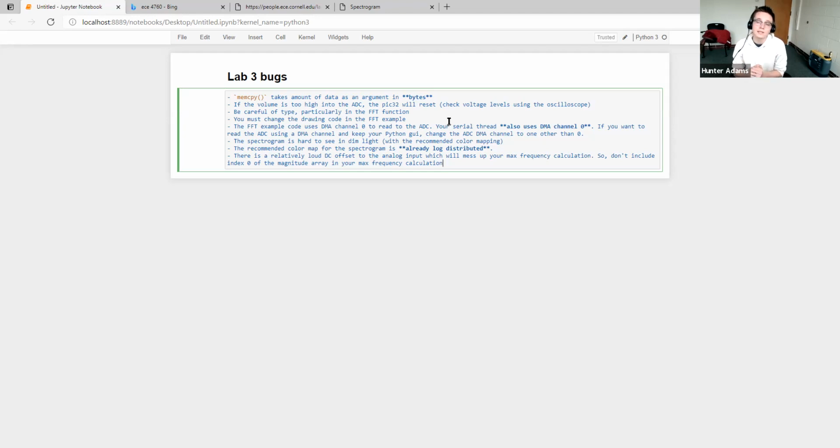And what you will find is the accuracy with which you can report the max frequency will improve as the frequency range of your spectrogram decreases, because there are fewer frequencies per bin in the output. So you can put in a constant tone at 400 hertz, and if you sample at 10K, you'll get some answer for max frequency which has a certain amount of error in it. As you slide your sample rate down to, say, 2 kilohertz, you will find that your computed max frequency is closer to what you expect it to be. 400 hertz was, I think, the example I used. Make sense?